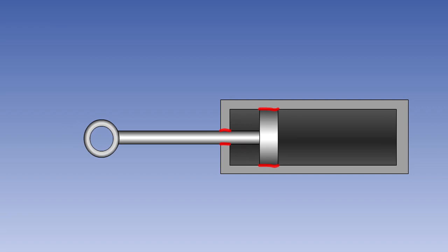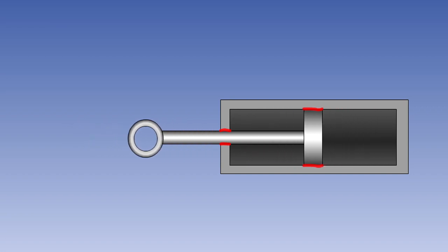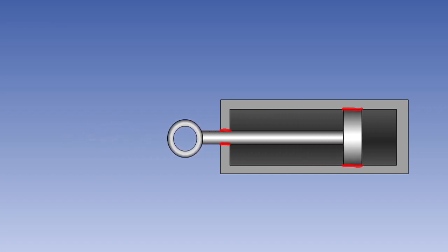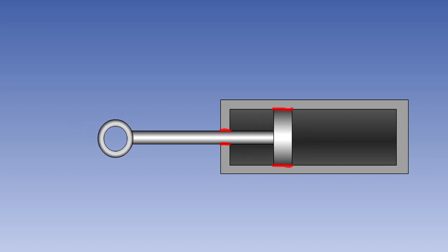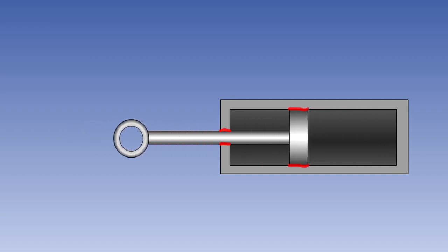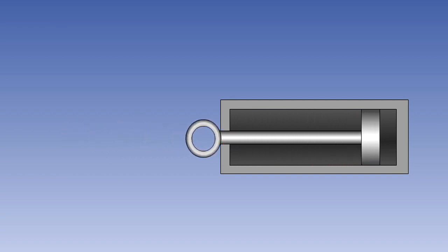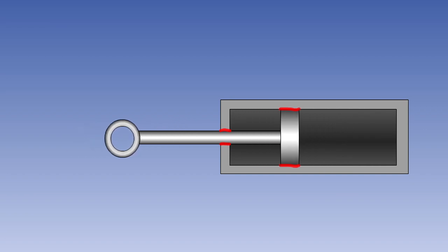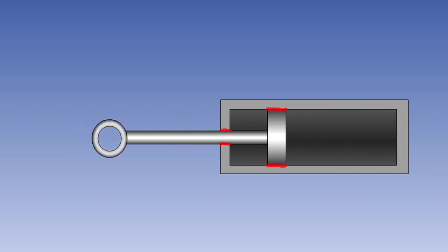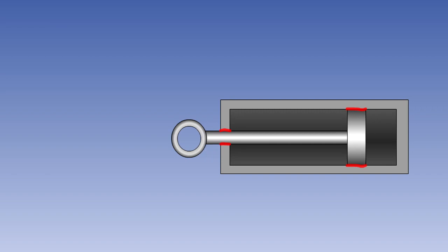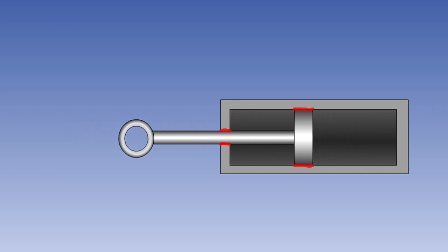The efficiency of a hydraulic system is governed by the resistance to motion encountered by the fluid. Force is expended in overcoming static resistance, which is friction in cylinders caused by moving parts, piston rods rubbing against bearings and seals, and by fluid rubbing against the pipe walls.